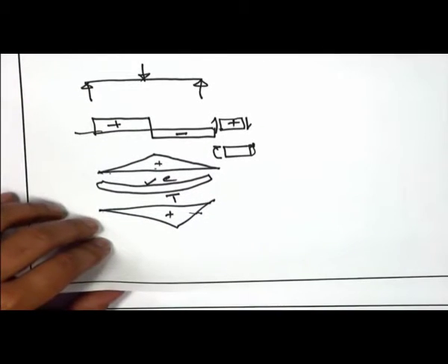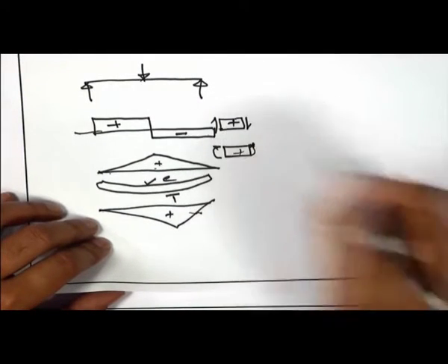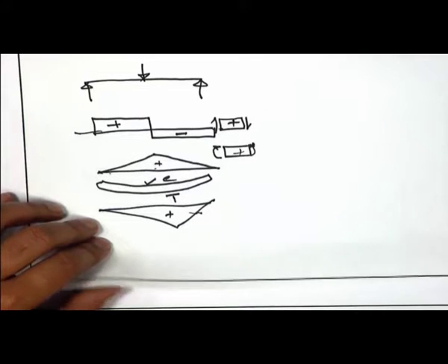Let me discuss with the students that perhaps you have understood. Before actually going to discuss the influence line, I have spent quite some time on the sign conventions followed in different books and also the sign conventions we will follow in our discussion. So, left up, right down is positive shear and sagging bending moment is positive for us. With this sign convention I have to proceed, otherwise there will be tremendous confusion about the results I am showing to you. Once again, these are absolutely arbitrary.